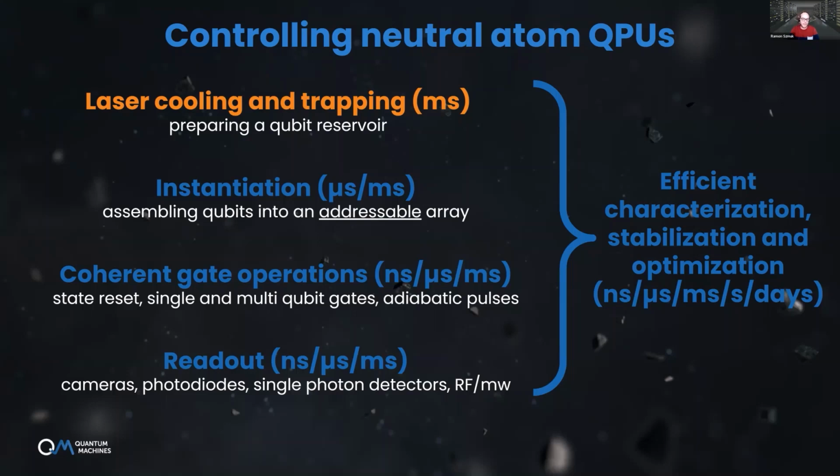And so here, it's typically not very complicated spectrally. It typically doesn't involve multi-tone pulses, but here there is a requirement to have all the pulses generated on a multi-channel system in a phase coherent manner, channel-to-channel coherence, intra-channel coherence, preserving the phase of pulses from gate to gate, and from channel to channel.